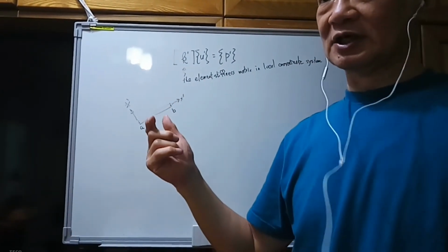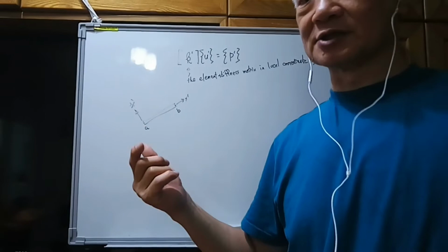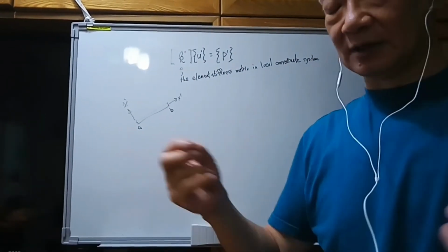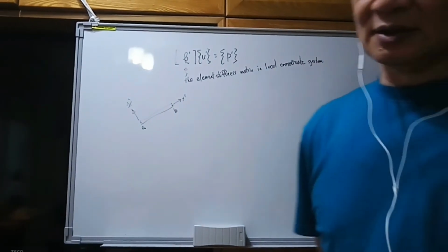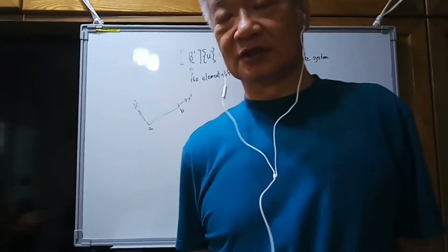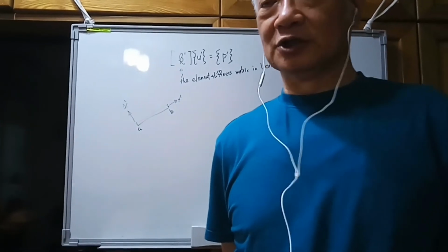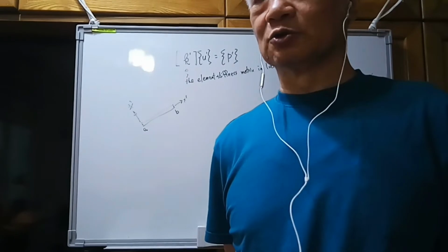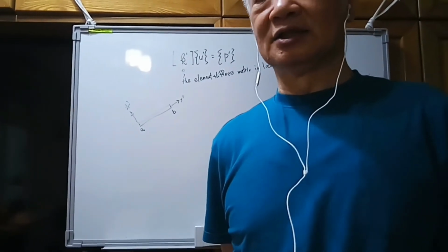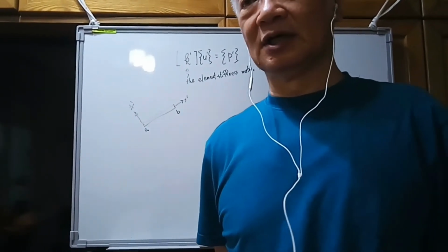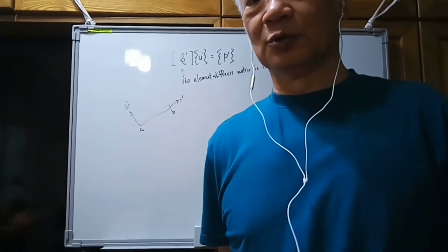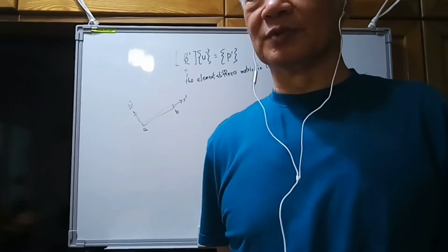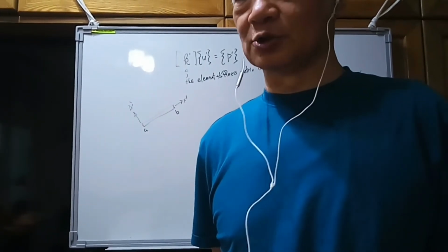If we consider the space truss problems, the K prime is still 2 by 2, since for the space truss problems, each element is still a two-force element. For the two-force element, the only important deformation and the only important end force will always be along the axial direction.